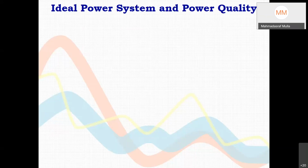If all loads are drawing current in phase with voltage and it remains sinusoidal, then we are utilizing the minimum possible VA capacity of the supply transformer, and the loading of the cable connecting the supply transformer to the load, the RMS current we are drawing, is the least possible.